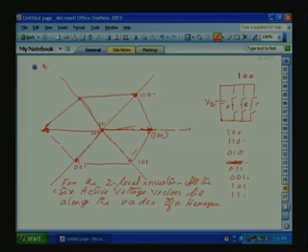Okay. Now, we want the voltage with PWM, the average variation of the voltage space vector, such that the tip of the voltage space vector moves along a circular trajectory. So, how can we generate it? We can only use these combinations.